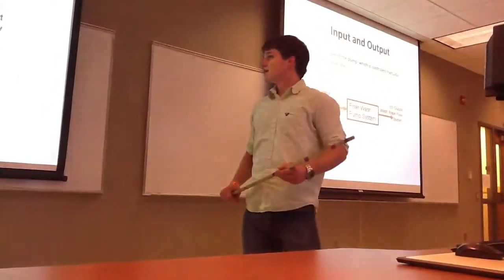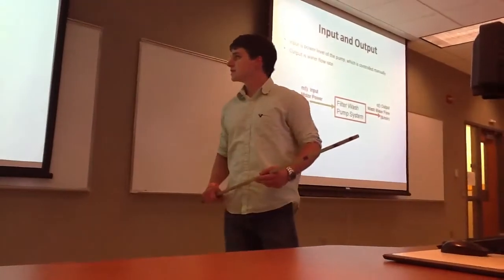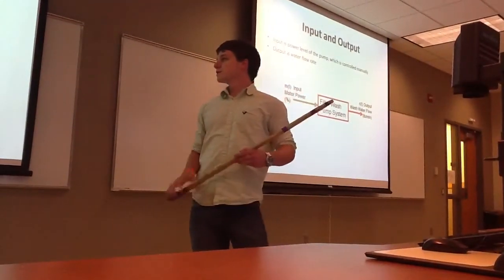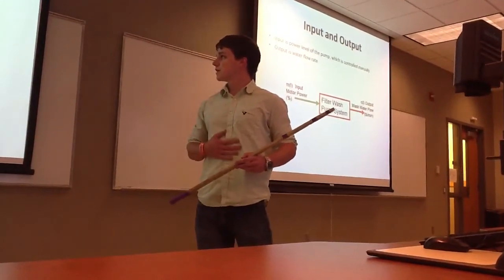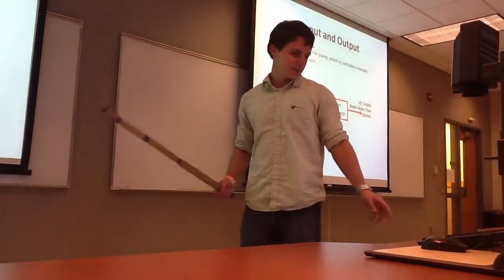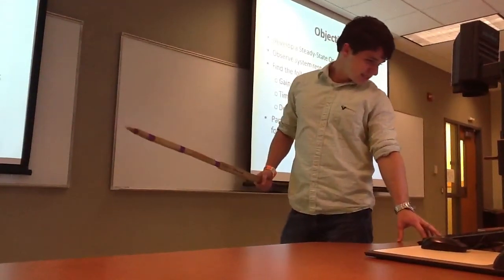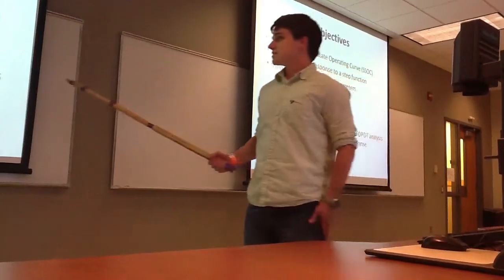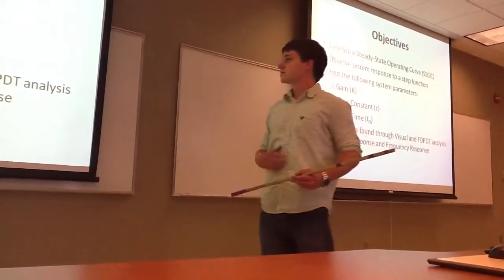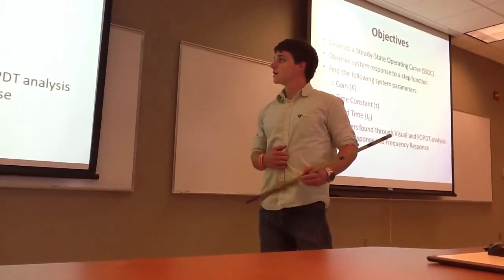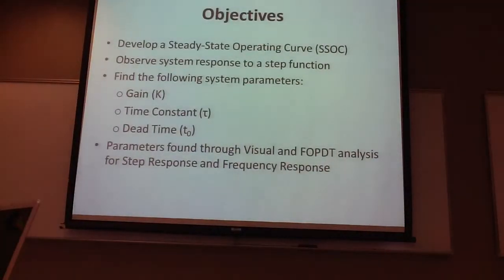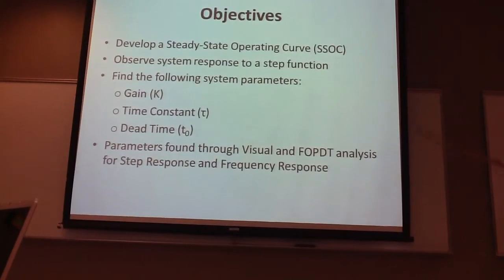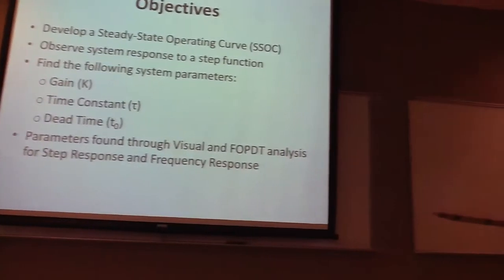We have a motor input in percent, which goes into the filter wash pump system and outputs water flow in pounds per minute. The objectives of the SSOC were to observe the step response and to get the gain, the time constant, and the dead time for the step response.